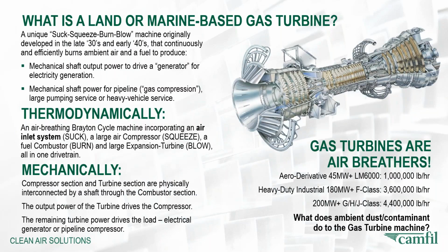My name is Jim Noordermeer, and I'm here to provide a brief introduction on what a gas turbine is, as a lead-in to Camfil Power Systems' air inlet filtration industry. So what is a land or marine-based gas turbine? It's a unique suck, squeeze, burn, blow machine, originally developed in the late 30s and early 40s, that continuously and efficiently burns ambient air in the field to produce either mechanical shaft power to drive a generator for electricity generation, or mechanical shaft power for a pipeline, say gas compression, large pumping service, or even heavy vehicle service.